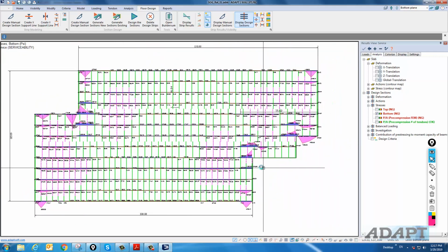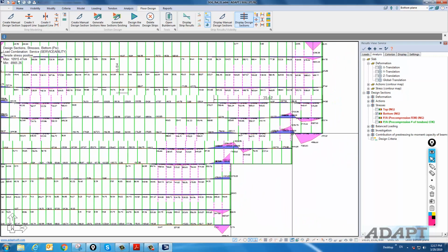And what that might be caused from is the fact that we're forcing a deformed state of a corner upward using these applied displacements. Well, in reality, as the volume changes at this location, that corner or joint might develop cracking to relieve stress that's developed by the uplift of the slab. So you can't have this corner really deform the way that we're forcing it to under displacement.